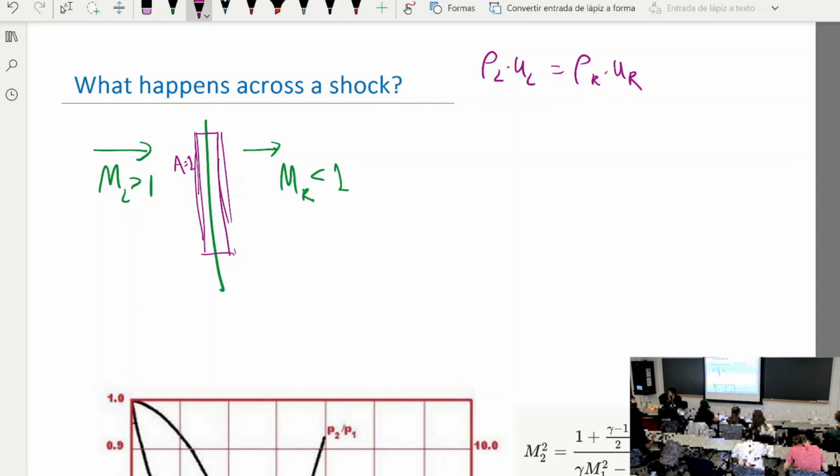That's simply mass conservation, right? The velocity across the shock wave decreased, so the density has to increase. Because otherwise, in this very thin layer, there is no way for the mass to accumulate or decrease inside. Right? Okay, so let's just denote that as m dot over the shock wave. It doesn't matter left or right, it's the same quantity.